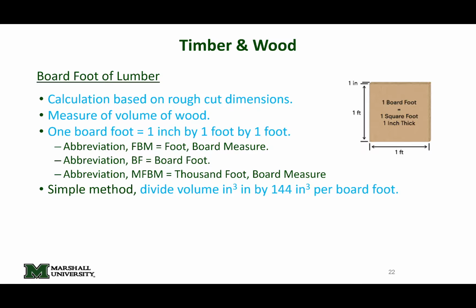And the main value of it is if you're doing a given project, like for example, let's say you're building a shed in your backyard. You figure out how many 2x4s you need, you figure out how many 2x6s you need, et cetera, and you ultimately arrive at a computation of board feet. And I'll show you how that works here in a second. But the number of board feet can be used as a cost estimation tool. Lumber is typically priced as a cost per board foot. So being able to distill a given project into how many board feet I need gives you a pretty simple way of figuring out how much that lumber is going to cost.